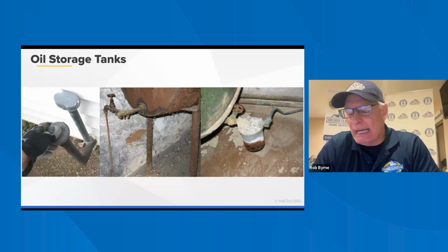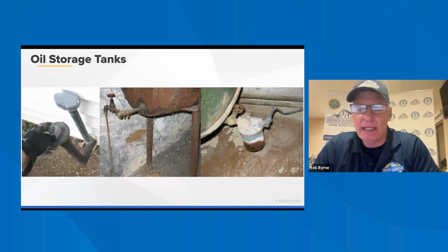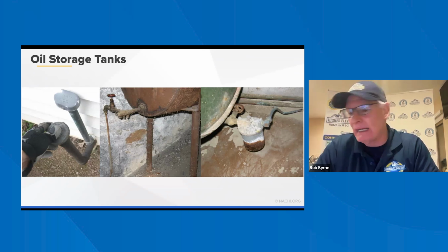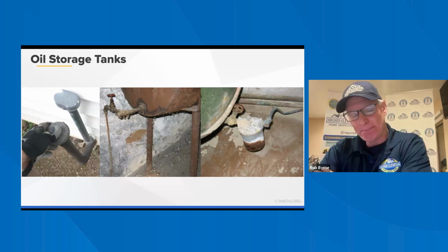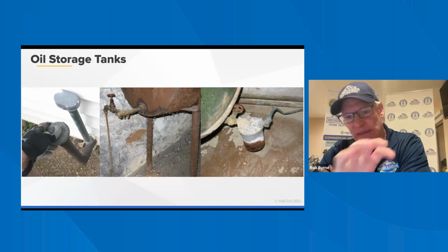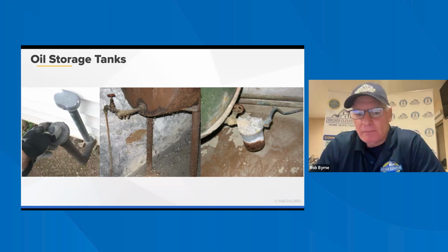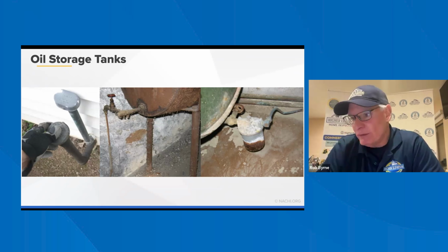We've done houses where they had multiple oil tanks outside, in excess of 1,000 to 1,500 gallons. They had multiple 500-gallon tanks in the ground, and just an absolute nightmare. So be very cognizant in your inspection of this potential buried oil tank or even an old tank.